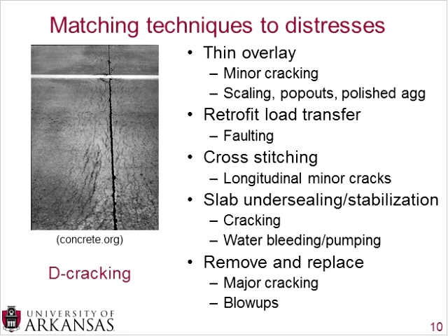As I mentioned, cross-stitching will alleviate future deterioration of longitudinal minor cracks. So if you just have some small longitudinal cracks, you can use the cross-stitching in order to prevent those cracks from becoming more severe.